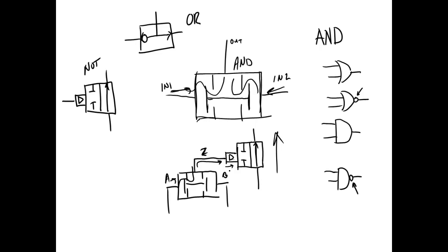And how much opposition a pipe has depends on how fast we try to move things through it. So every conductor has opposition. And if you put current flow through opposition, you get pressure loss, which they call line loss. So the lower I can make the speed, the less line loss we get, right? Does that make sense? So what they do is they step up the voltage to thousands of volts to transmit it. And then when it starts getting close to you, they start lowering it down for safety.